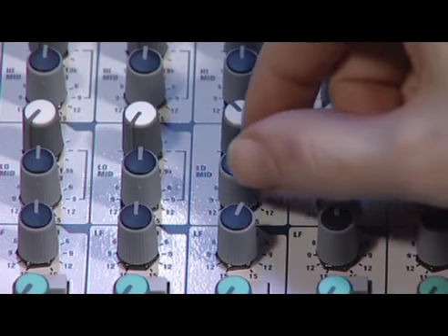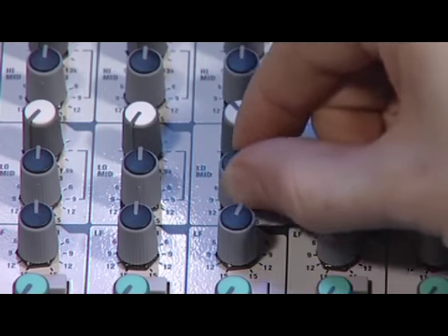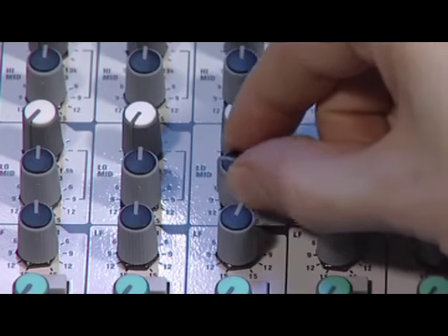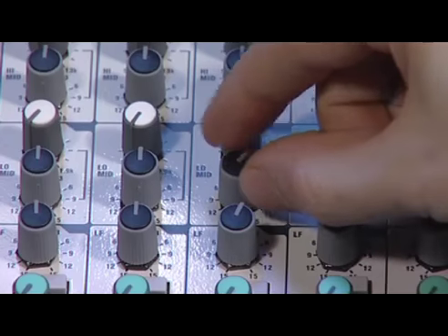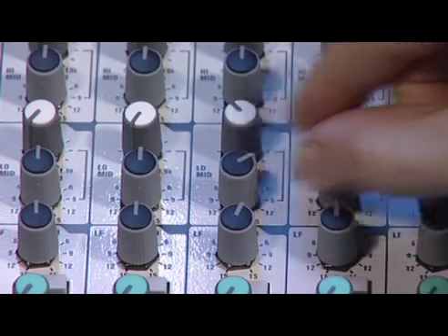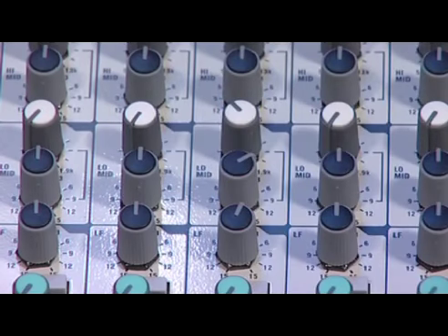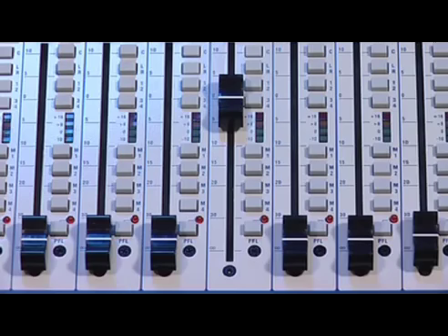Now rotate the knob from boost to cut. Choose the amount of cut that sounds best. Even a small amount of cut can have a hugely beneficial effect. Remember that EQ is actually frequency selective gain. Whenever you're boosting a frequency band, there's an increased danger of feedback, so just make sure any channels with open but unused mics are closed, and that the amplifier levels in the auditorium aren't too high.